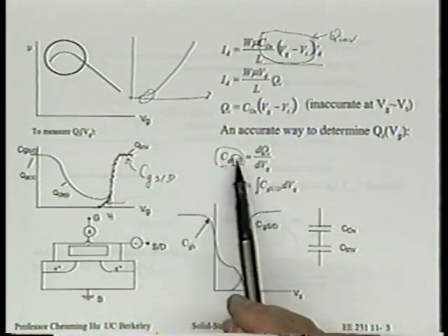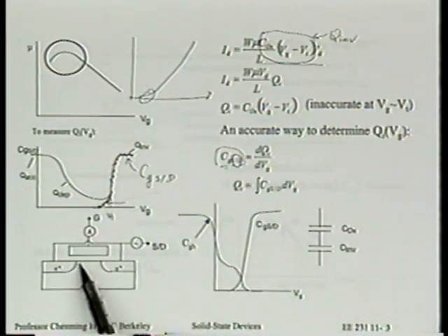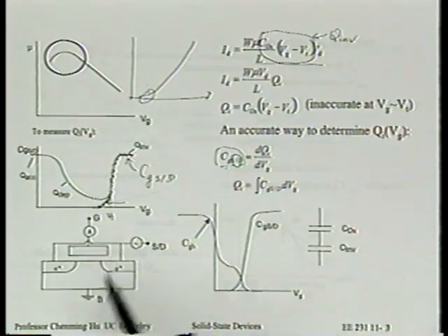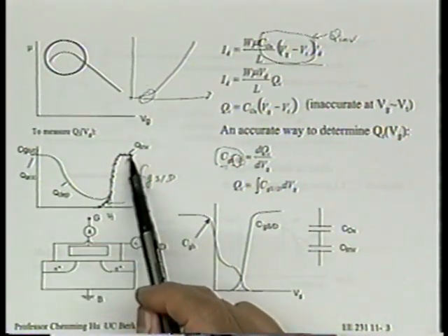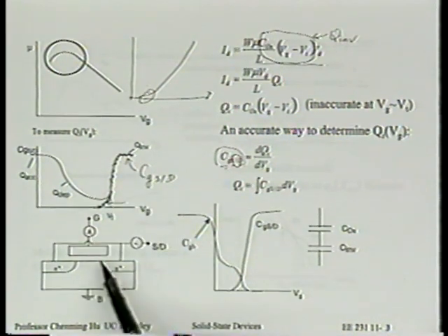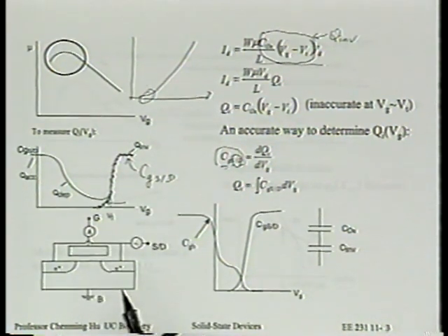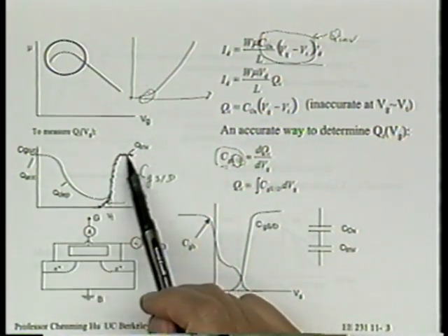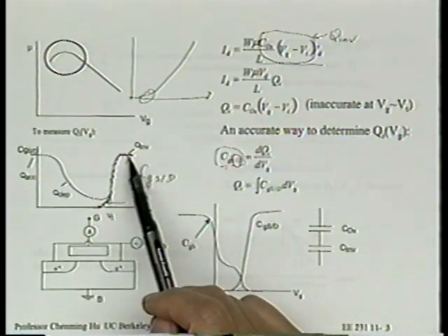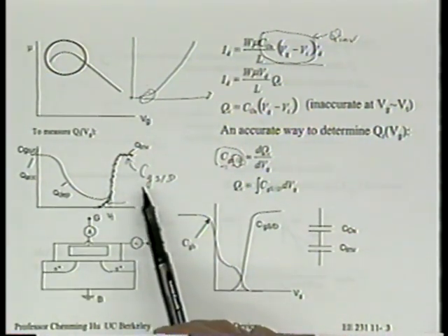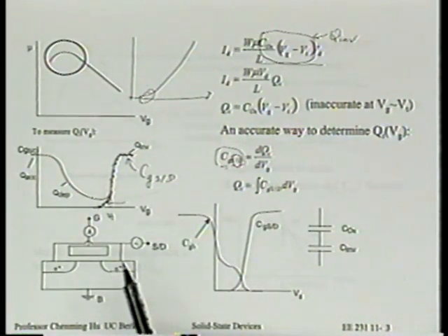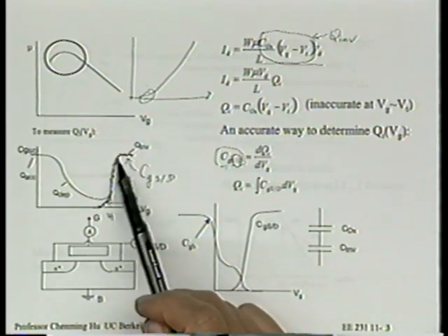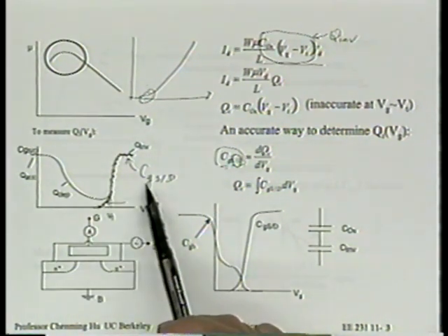And that will show up as between CG and SD, because the charge in this inversion layer is supplied by source and drain. In fact, that's the only reason we will see the so-called low-frequency CV, even though we may be using 10 megahertz for this measurement, right? Because the source drain are supplying the charge. So this current we see is the result of charge coming from the source and drain. Do you follow this? That's what we call the CGS/D. All right? Same thing. Any capacitance due to the inversion layer charge will show up as CGSD.